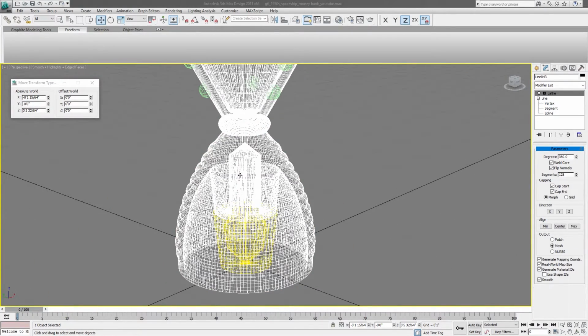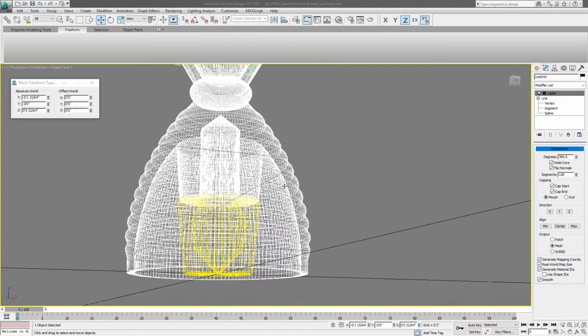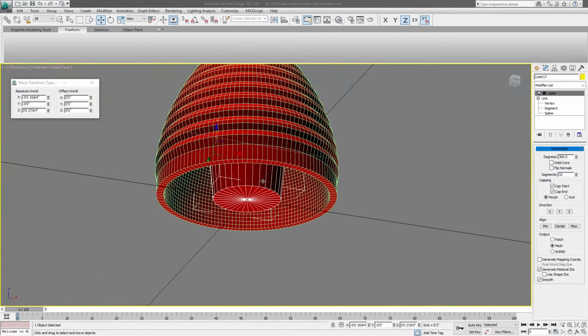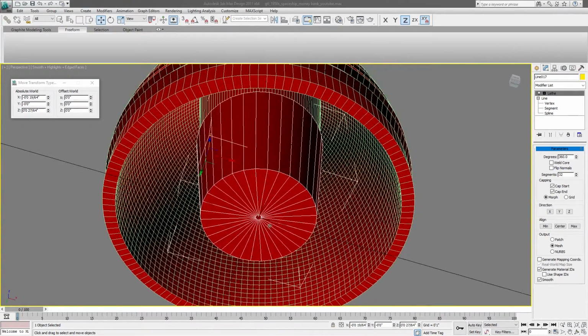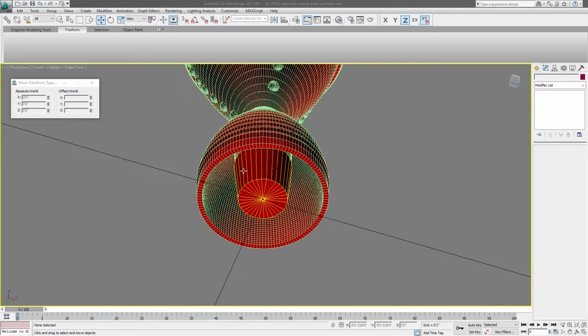If I hit F3, that'll go to wireframe mode. You can see this whole pile of lines here. This is the actual nose cone portion, which holds the smoke for the rocket stand. Some people had issues on the bottom. We created support material in the model so that when you print it, you didn't have to add support. But I guess the gap between the two had a lot of issues. So in the end, I think we just took this out when we uploaded it, or you'll see that you have to add support below the model for it to actually work.